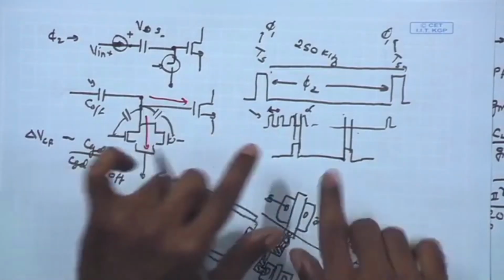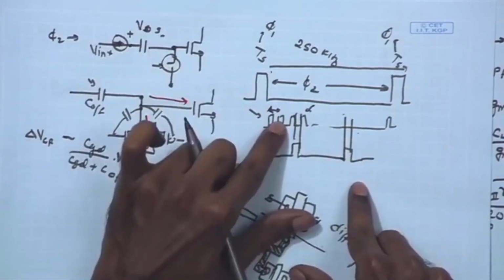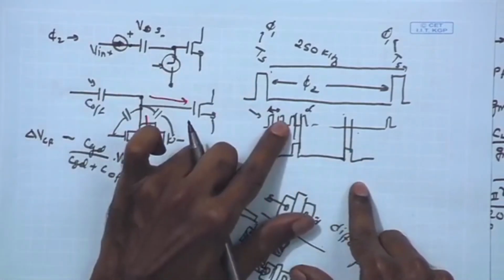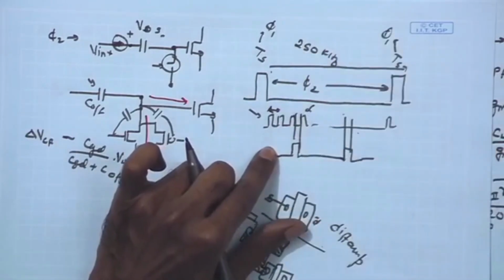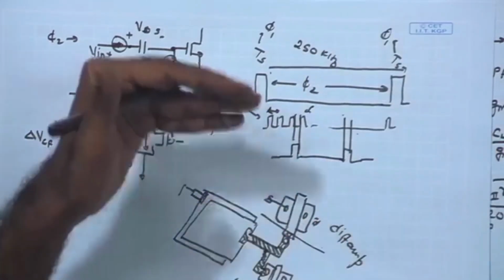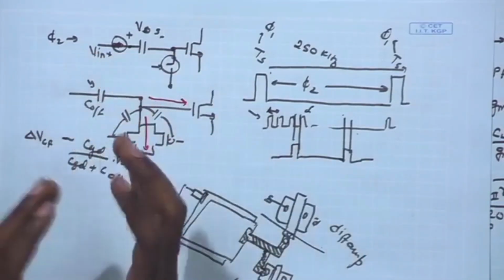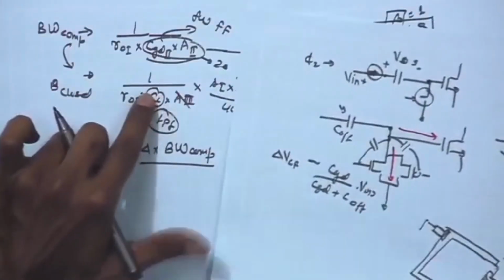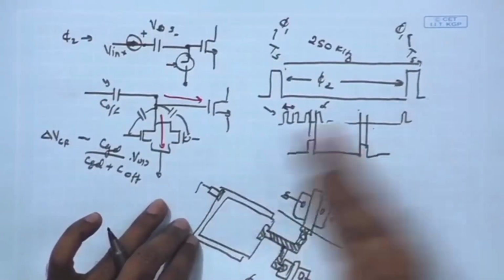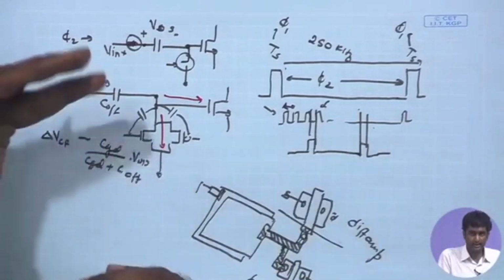So, you can see how the circuit operation or the circuit level results can impact our control scheme: when to apply the phi 1 pulse, how many phi 1 pulses to apply, and then accordingly what the digital control scheme is. All these things get linked together very tightly. If you are messing up some circuit implications or metrics by making this amplifier faster for the closed loop feedback, we may be dissipating more power over there, or maybe making the design more complicated.